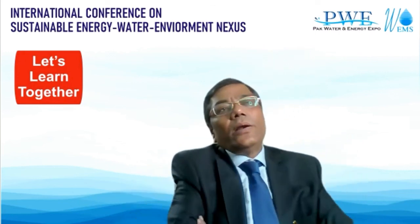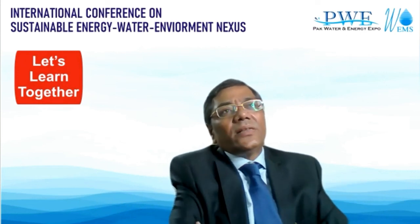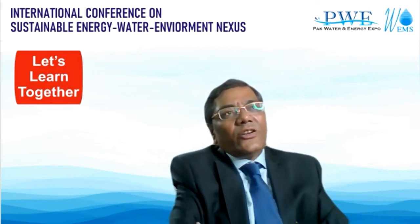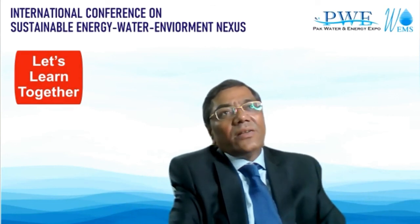Okay, another question is how we can use filter press sludge from an effluent treatment plant for safe disposal or energy production. In a filter press, basically, you are dewatering the sludge. Normally, 20 to 25% concentration remains, and the other water is dewatered, and then you have to dispose of the sludge or incinerate it.